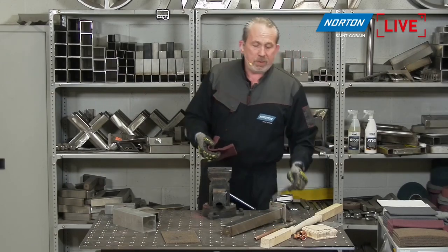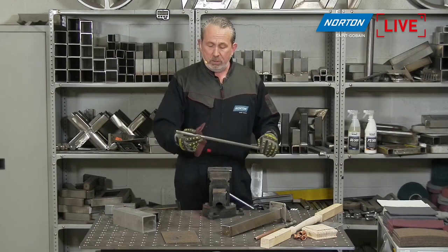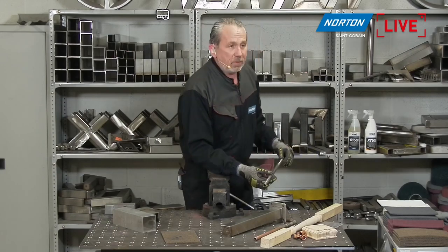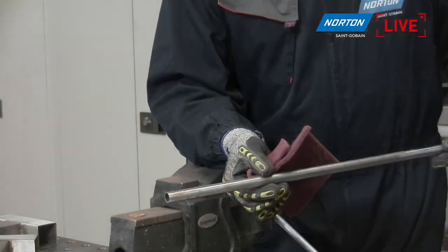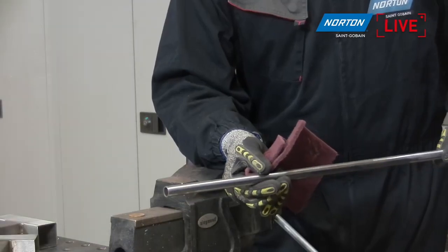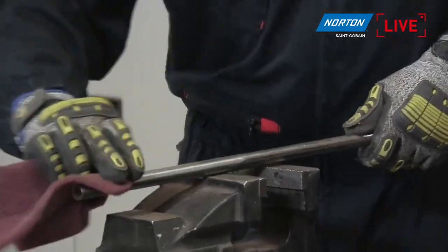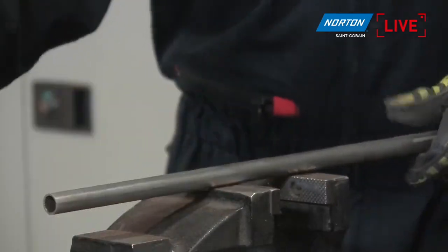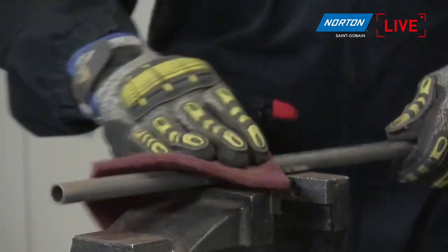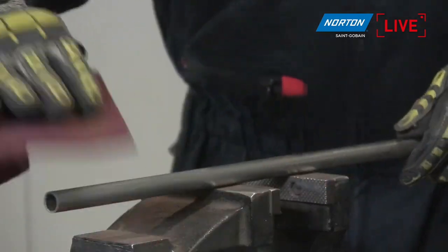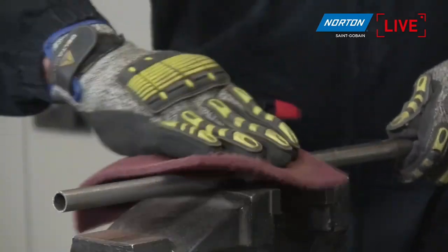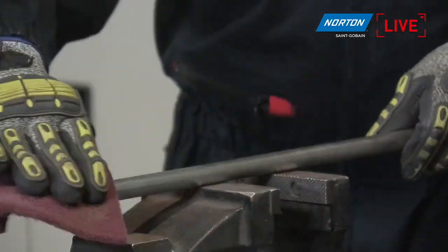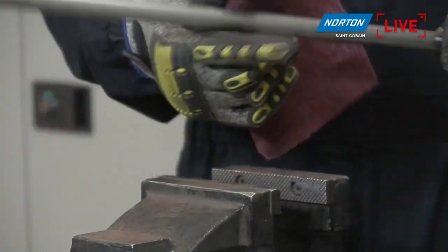So not only on copper, but even materials such as this, a carbon steel. So this is a carbon steel pipe as well. Again, with some rust and corrosion on there. If we could just zoom in on that on the camera, please, Martin. We can see there's a load of rust and corrosion on that steel. And again, with a very fine pad, really, really quickly, we can take that off. So we're respecting the round of the pipe. We're not going to distort the shape of that at all, but really easily, with your hand, you're able to clean that rust and scale off that pipe really, really quickly. Give it a really nice finish, I think, as well.